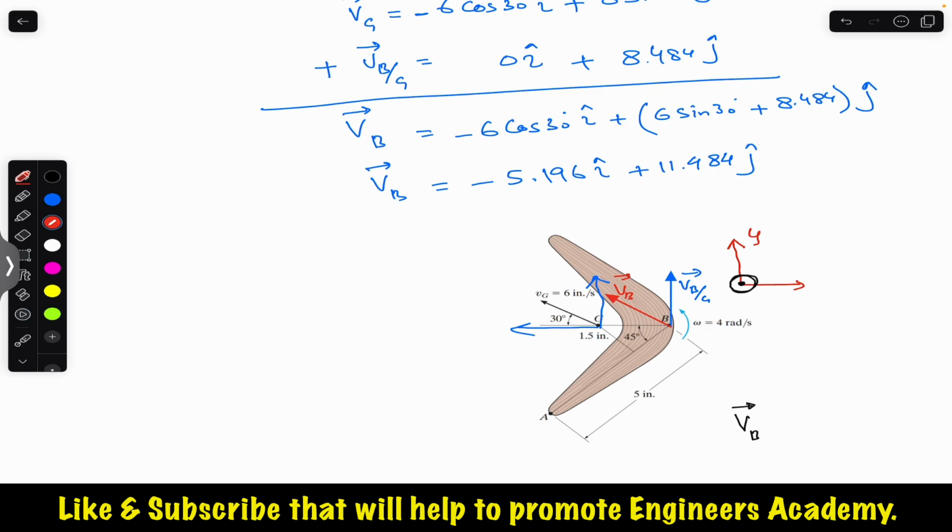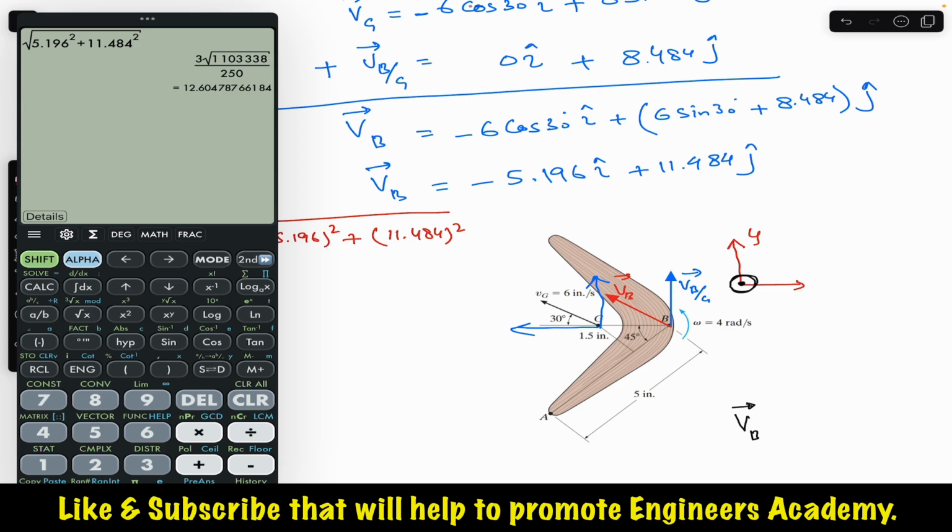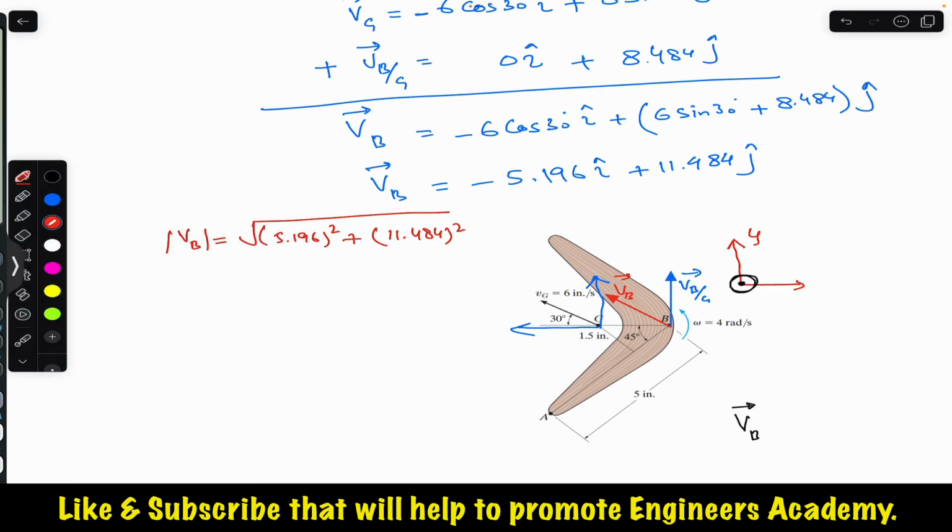And we can find the magnitude of VB. VB in magnitude will be equal to, we can always apply the Pythagoras theorem, so taking the square of both of these, that will be 5.196 squared plus 11.484 squared under the square root. This gives us 12.605 inches per second.